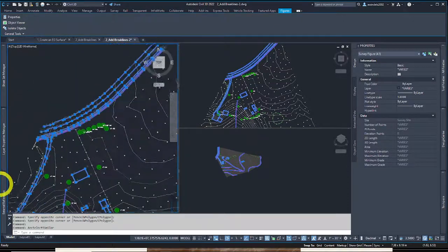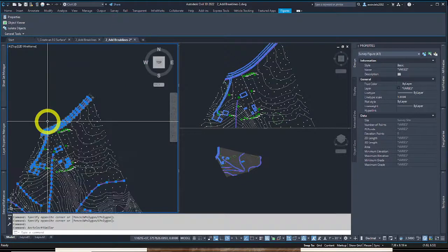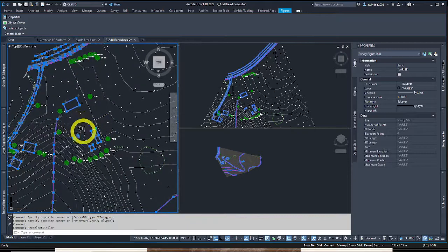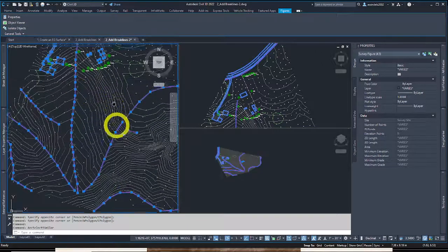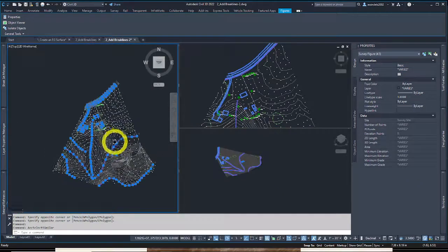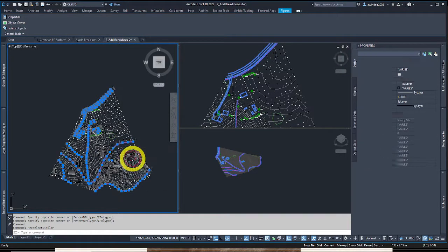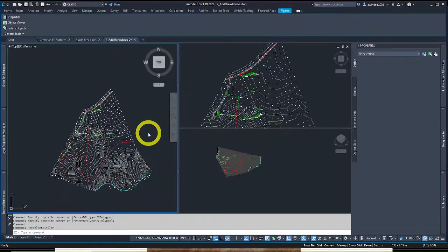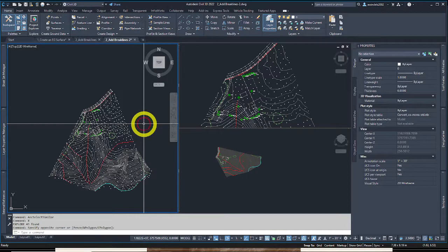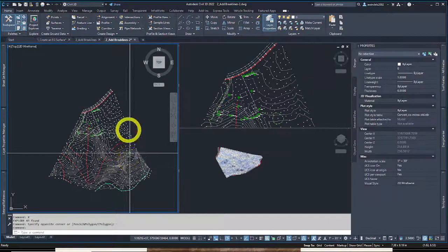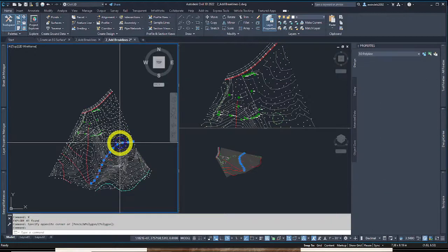I change them to 3D polylines and leave them in there, or I change them from 3D polylines into feature lines, and I use them that way as break lines. I get rid of these survey figures because they're kind of unwieldy to edit later on to change symbology and various things. So I did already add them to the surface, but a lot of times initially I'll grab them, hit X for explode. I'll explode all of them. So they're already defined in my surface, so that's going to update my surface. Usually I didn't do that part first, so it goes back to being a dumb surface without break lines.